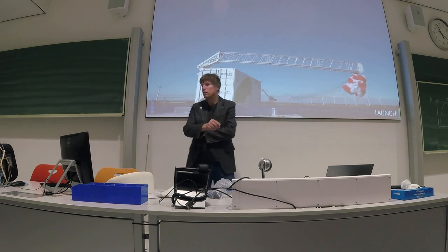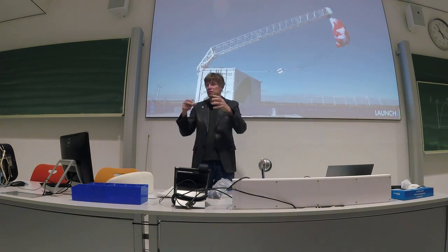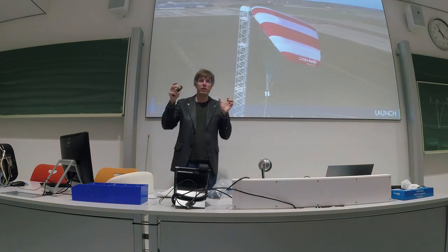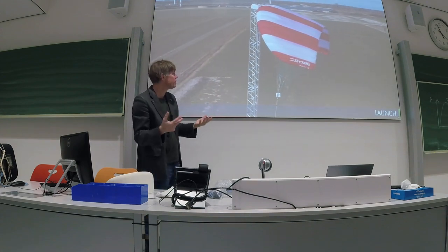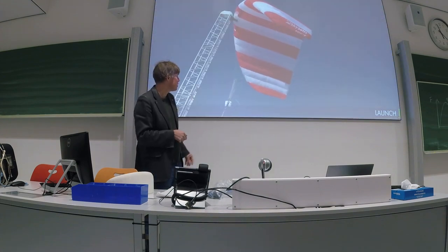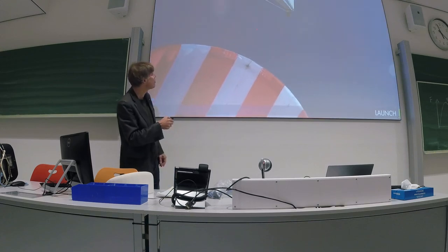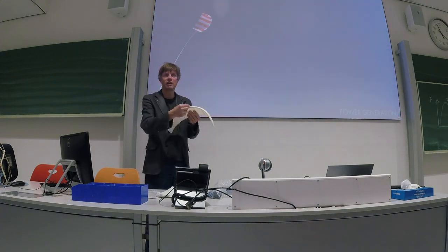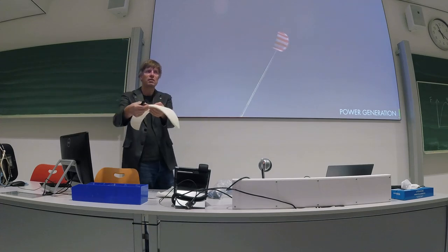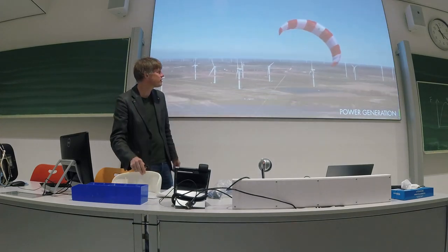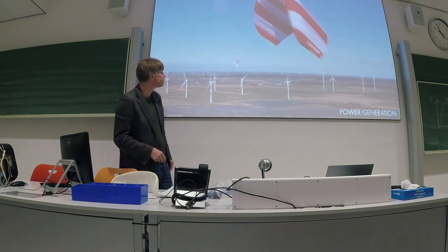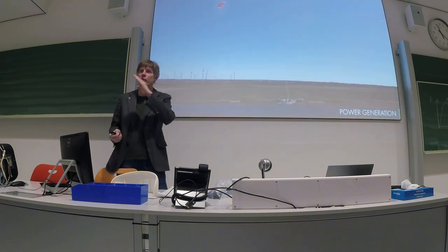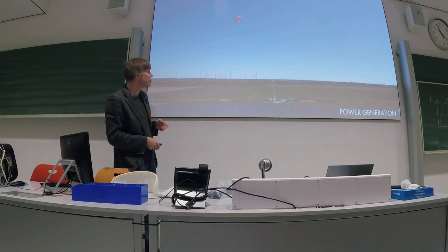And this is how launch and landing works. You see that the kite is deflated. It has these openings here, which, when faced into the wind, inflate the kite. And the kite, here's the control unit, can then take off. There is a fifth line, we call it, attached to the leading edge, which allows the kite to be pulled towards the launch tower. When you watch these videos carefully, you see this fifth line being dragged around. It's in addition to the main tether.